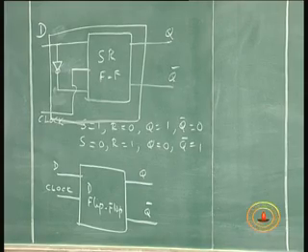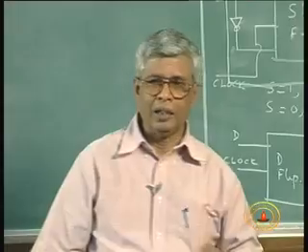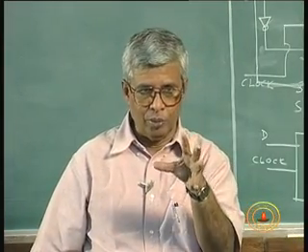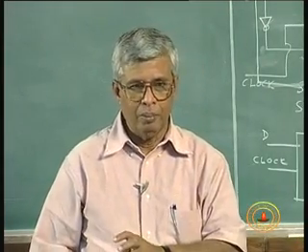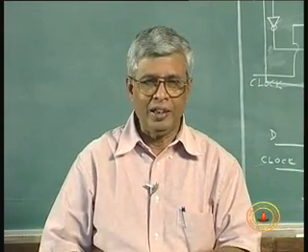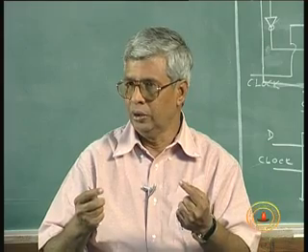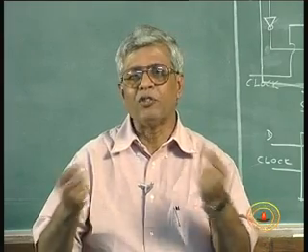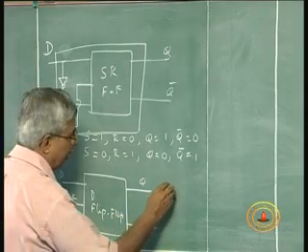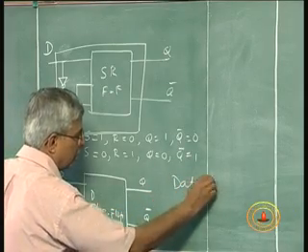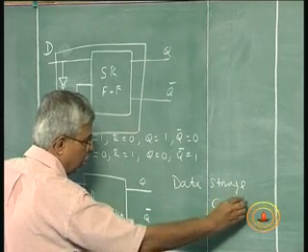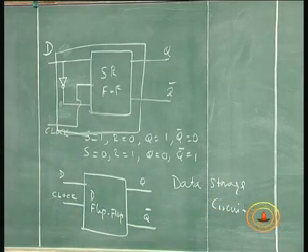storage. When you say memory, for example, in a computer or calculator, any circuit, it consists of these. Of course, the memory is a huge memory these days, but individually, whatever the size of a memory, finally it is the bits to be stored, and bits are stored in a D flip flop. So, the D flip flop is very frequently used as a data storage device or circuit. That is why it is called a D flip flop, D for data.